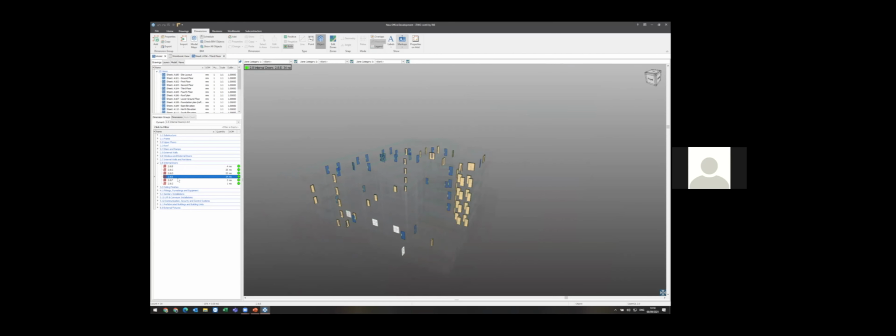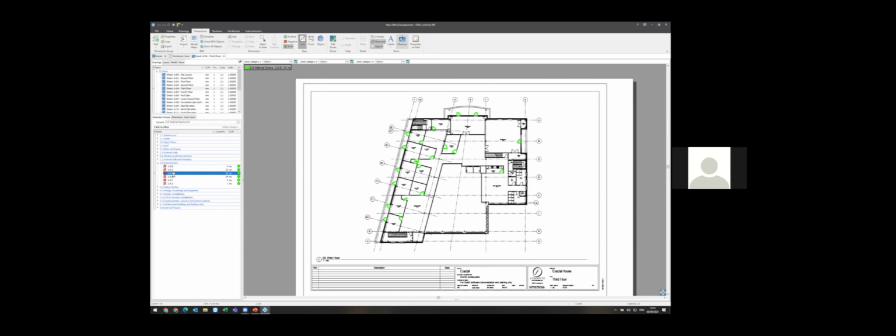So 2.8.E are the glazed doors. As part of our QA process, if we're using a DWFX, I can jump across to the 2D sheet now, and you can see that that takeoff there of the 2.8.E is automatically highlighted on that drawing. So I can click through onto the other dimension groups and see where they appear as well. And if I hover over each, it tells me what it is.